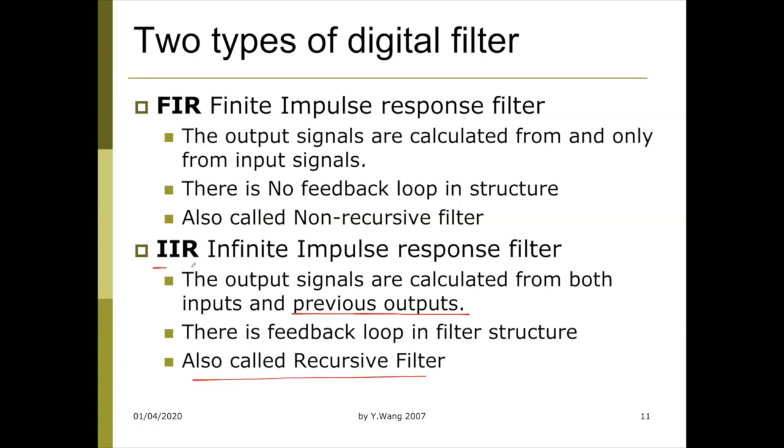Well, there are some advantages to both filters. FIR is straightforward to implement. There's no problem with what we call instability because there's no recursion. You don't get this positive feedback. In a music sense, everybody has probably experienced this positive feedback problem. Is that proper terminology?